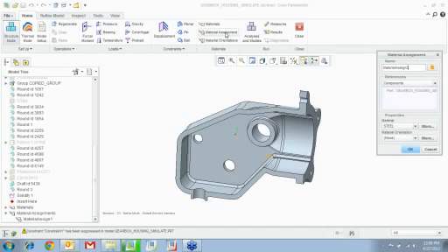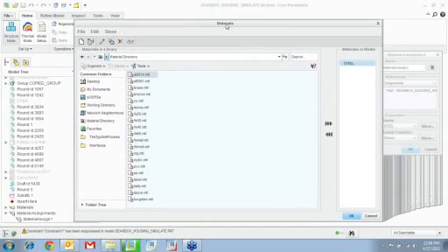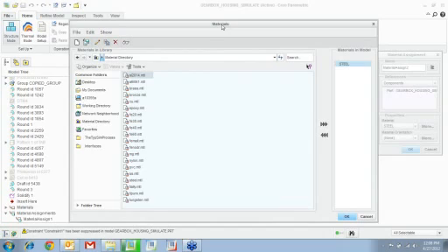So you go ahead, click on the material assignment box, click more on the material, and you can go ahead and pick whatever material you want from this list. Now a lot of people have been asking me as to, hey, are these the only material? Can we download something? Yes, there are a lot of free downloads available. I can ask Rosalinda to shoot you a link with a lot of these free downloads of materials.